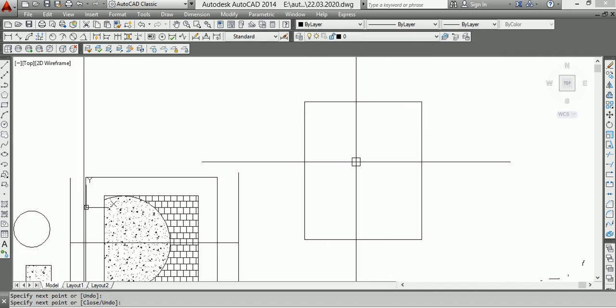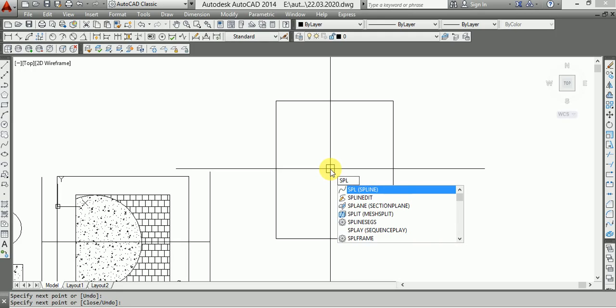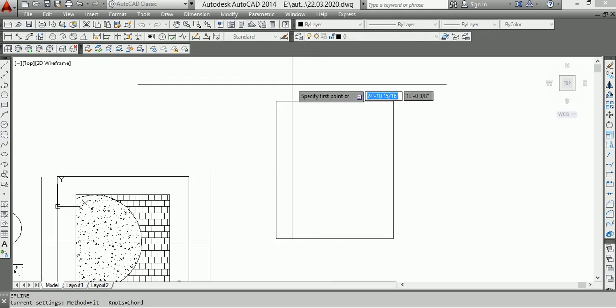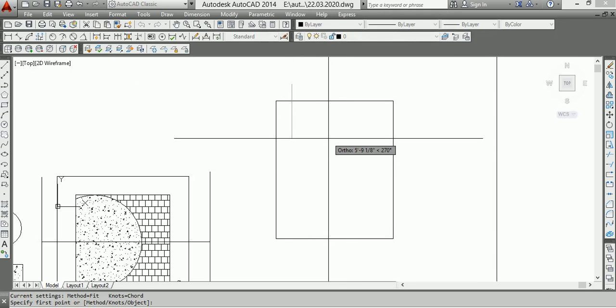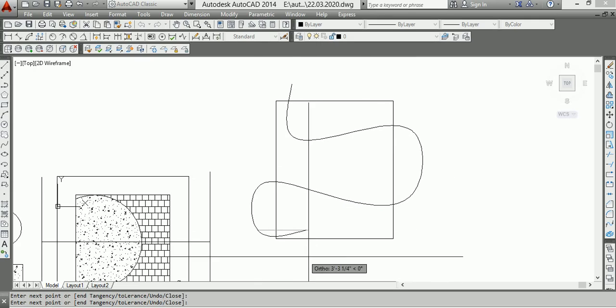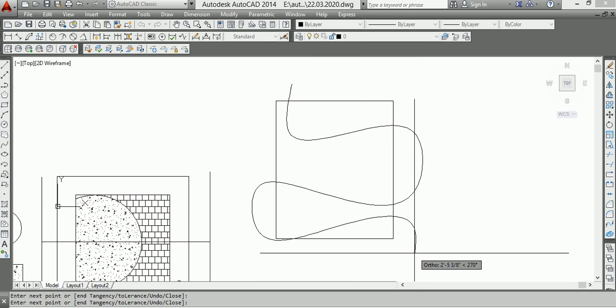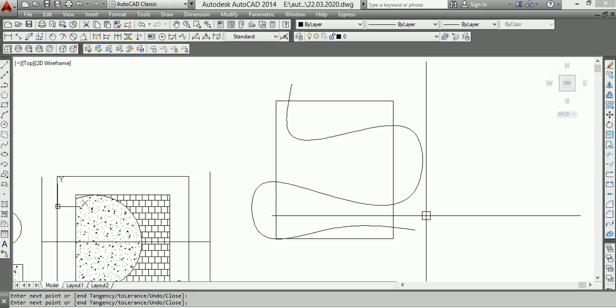Okay, so if you want to draw any curved line in AutoCAD, the command is SPL. It is the command for spline. Spline is a curved line having many editing points. So SPL space, and then you can click. You see, since my F8 command is active, that means only the straight line is active. That's why I cannot draw at my will, space to enter the spline.